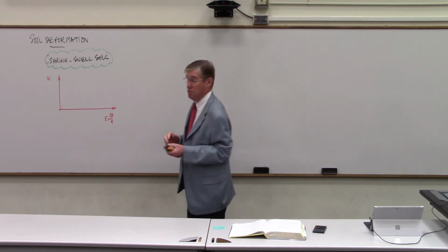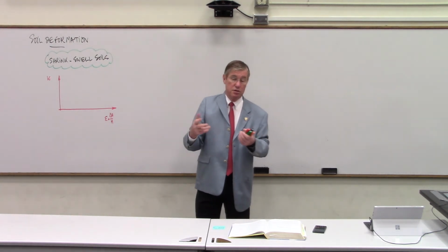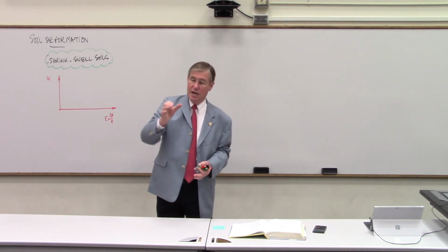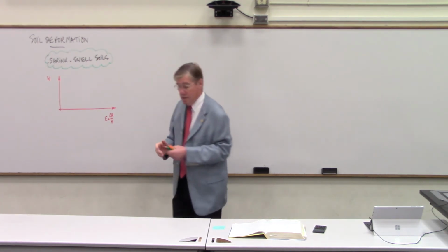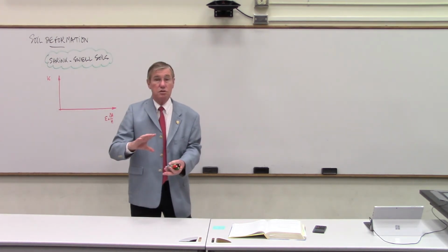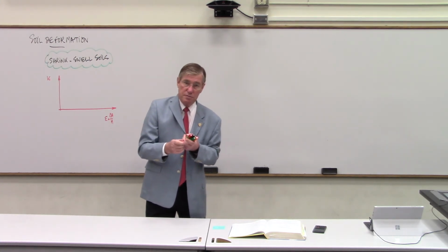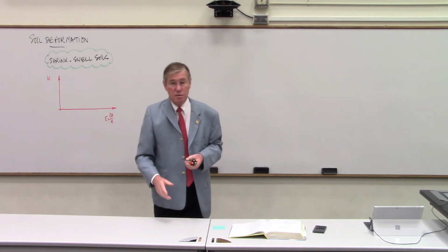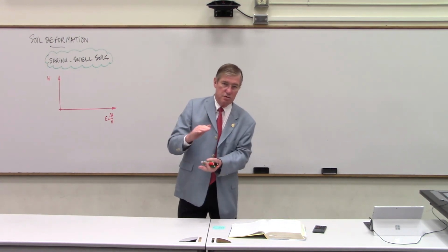And so you can do some, let's say you go to the field, you come back, you have a sample, it's in a Shelby tube, you extrude it, you cut it, and now you have a cylinder about that high, that big around, nice geometric shape, and then you weigh it, and you measure its dimension, the height, the diameter, so you know the volume, and you know the weight. You then let the sample dry on the table, sits there, and you come back an hour later, you weigh it, you measure its dimensions.